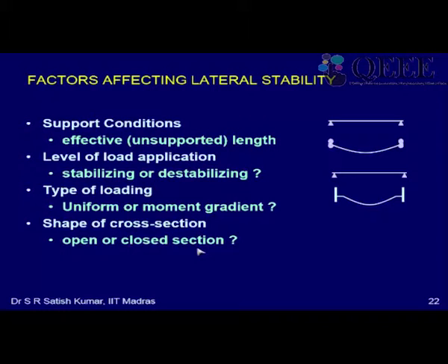Okay, so IYY will be, let's say we neglect their moment of inertia about their own axis, but when you shift by parallel axis theorem, IYY will be approximately 2 times IYY of the section about its own axis plus 2 times A h square, right, where h will be the distance of the web from the center line.